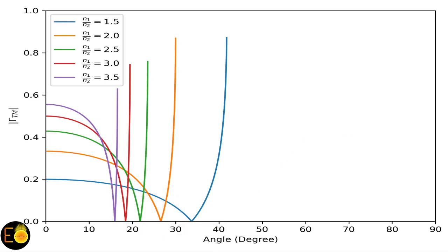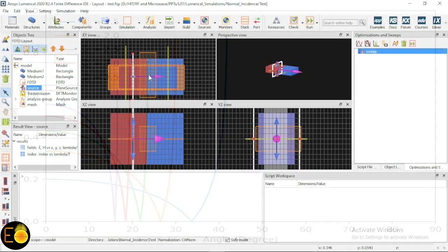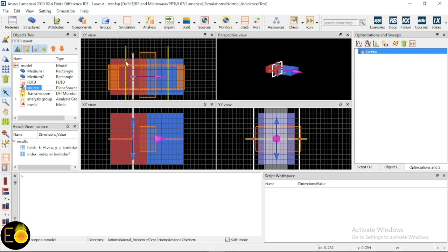If you are new to my channel and this is your first tutorial on FDTD Lumerical, and you don't know how I have constructed these structures, please refer to my previous videos on the basic structures and the simulation setup for Lumerical FDTD, or you can click on the card to go to my previous videos. Anyway, Brewster's angle is the angle at which the reflection will be 0, and it can only be observed in the case of TM polarization, whereas in the case of TE polarization, it is not.